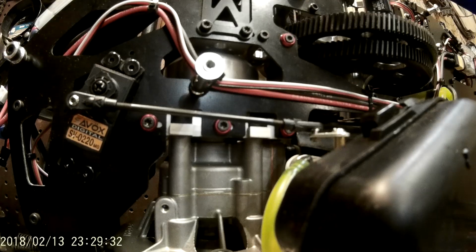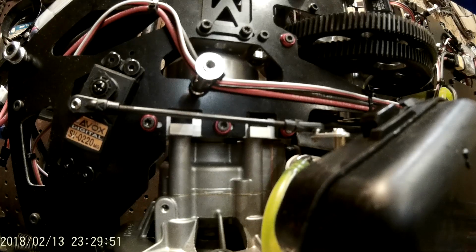One more thing that I wanted to show is what happens when you put the collective pitch at the center stick position and do a ramp up. So let's arm the flight controller. You'll see the throttle servo snap to the idle position. We start the engine. Now we're going to move the collective pitch up, well, yeah, we'll move it up to the center stick.